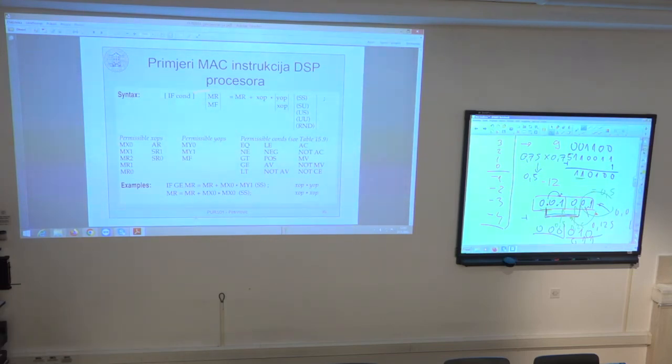Finally, this instruction can also be executed conditionally. And this table lists all 15 possible combinations of conditions. So equal, not equal, greater than, greater or equal, less than, less or equal, negative, positive, overflow of ALU, not overflow of ALU, carry, not carry, and so on. And so I need 5 bits to encode this condition, since the last combination is unconditional execution. Then 16 combinations is 4 bits, sorry. 4 bits because it is 16 combinations, okay.